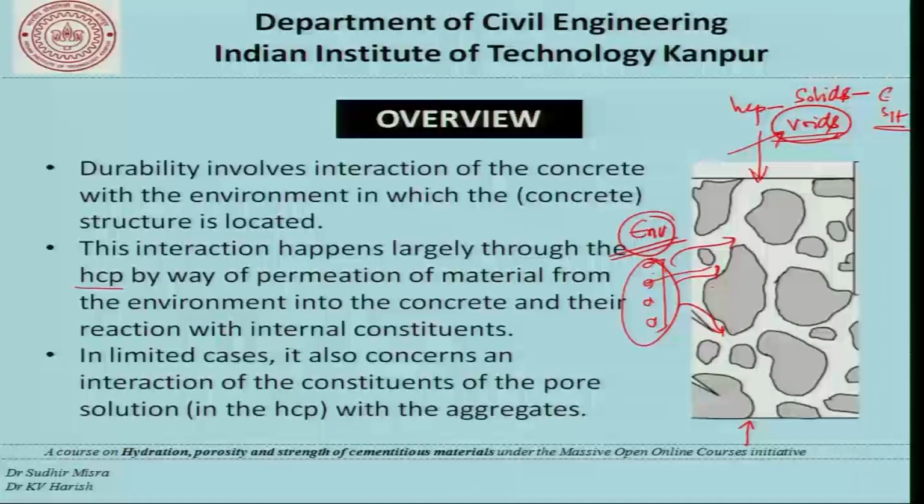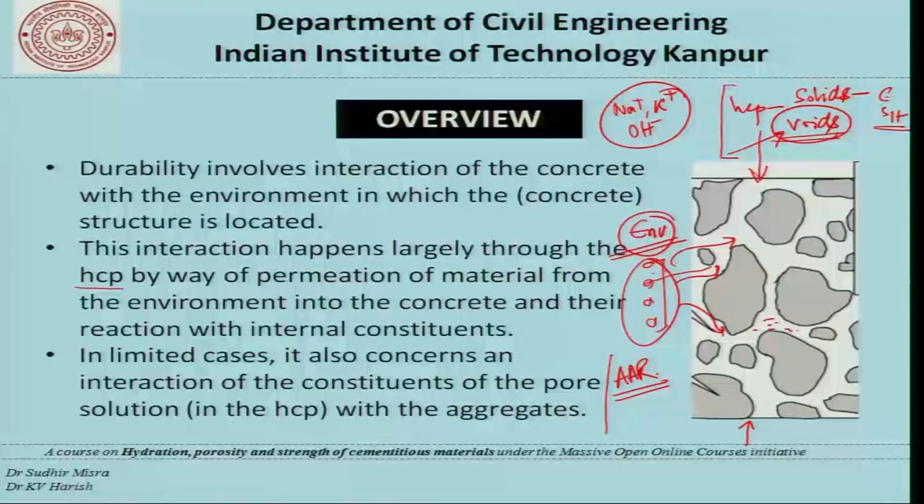In limited cases, it also concerns an interaction of the constituents of the pore solution in the HCP with the aggregates. This is particularly true with the mechanism of alkali aggregate reaction, where the hydration products themselves contain sodium and potassium ions apart from hydroxyl ions, and these are very much part of the HCP, and they interact with these aggregates, which in that case are reactive.